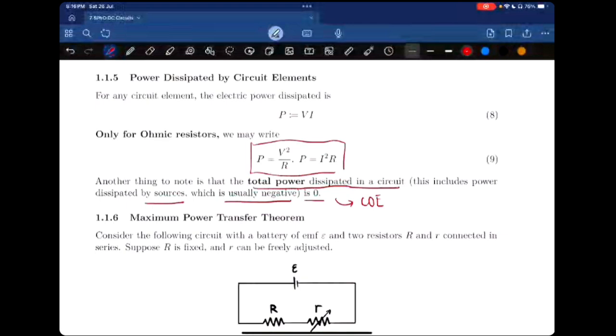Here, it's quite simple. You can just prove these using Ohm's law. For voltage, you just want to distribute the voltage such that it scales with the resistance of the two points it is connected to. For current, it is the opposite. You want to scale it like that. In practice you don't need this, but it's good to be faster by using these.